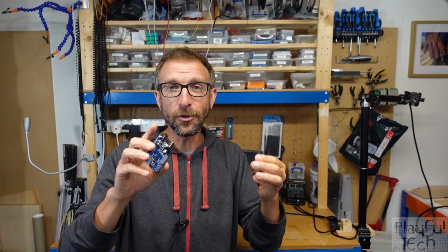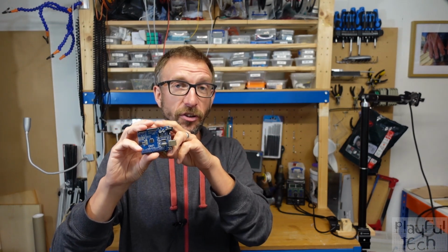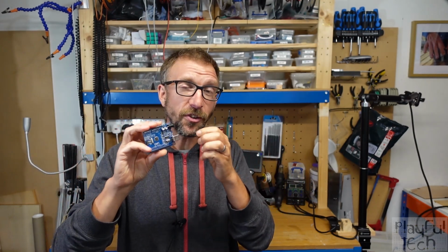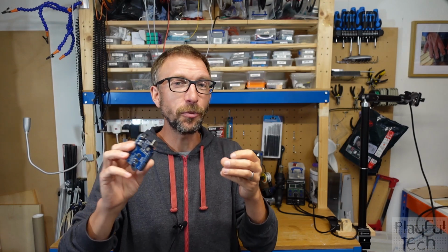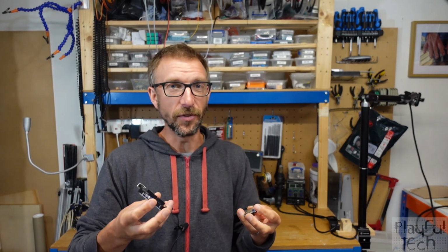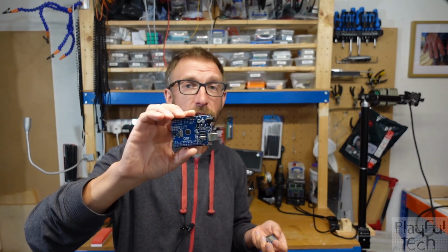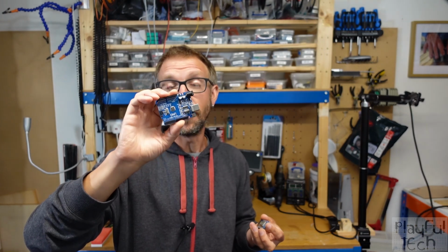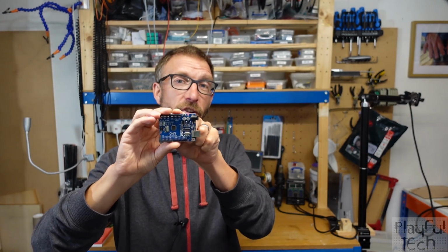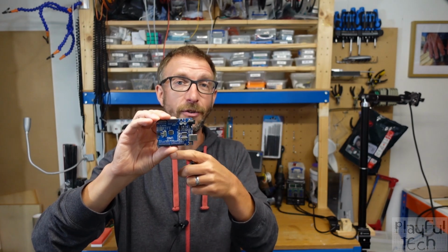Now, a low signal generally means that there's no potential difference between the voltage of the pin and ground. The voltage is 0. But what constitutes a high voltage differs between devices. And that's what we call the logic level of a device. So older boards, such as the Arduino Uno, Nano or Mega, are 5-volt logic level devices. So a high signal on the GPIO pin of this device corresponds to 5 volts above ground.